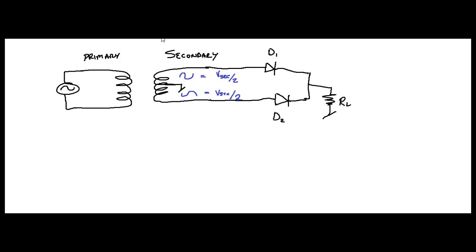Let's just go through it. So in one direction, when your primary is in the positive part, right? What's going to happen? This diode's going to be on, isn't it? So you're going to have a positive voltage here, right? That's what it shows right here. It's a positive voltage, right? So you're going to have a positive voltage here.